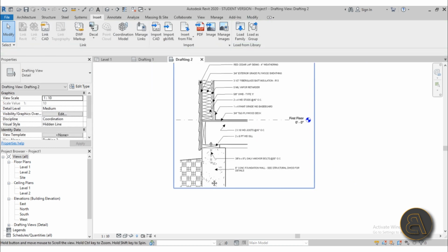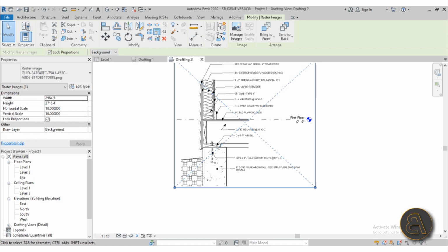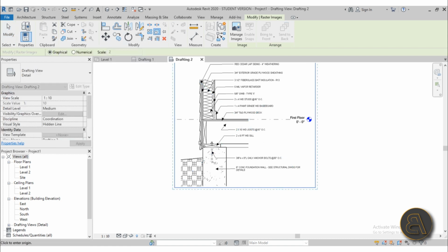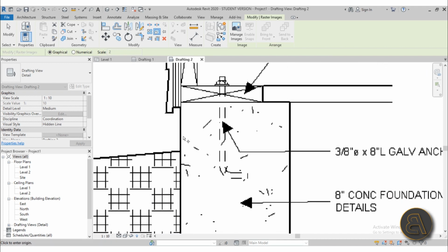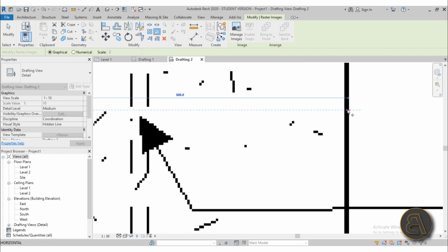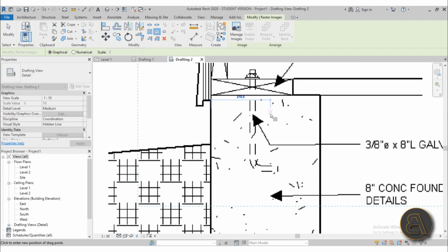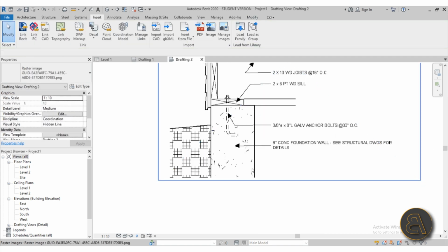So what I'm just going to be doing is I'm going to go here to just select it, go here to scale, or use the shortcut RE if you want. And then what you need to do is just select one part of the wall, so just one side, then go to the other side, and as you can see, it's like 500 millimeters currently, but don't worry about that. So just go to the other side and then kind of pull it towards the first point and type in 200. Hit enter, and there we go.